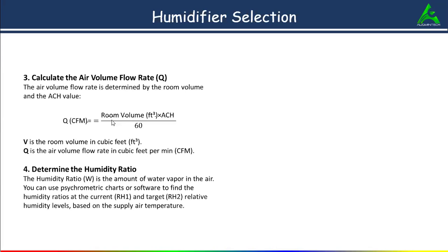Fresh air, in the sense that if people are continuously seated inside the room, they will breathe and carbon dioxide will increase in the room. If there is no proper ventilation, what the engineer will do, as per the standard, is send 20 to 30% fresh air from outside.